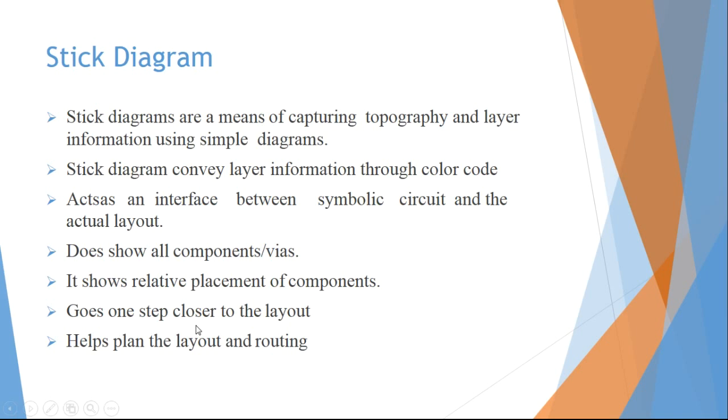It goes one step closer to the layout, as before going directly to the layout, we need to design the stick diagram to see the different connections. It helps to plan the layout and the routing. Mainly for this particular purpose, the stick diagram is most important.